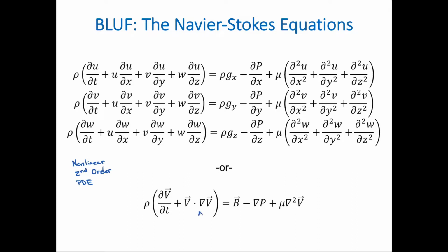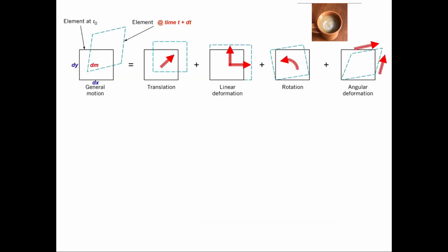So this is the del operator. We talked about it in lesson 24. This is the gradient, which is equivalent to the del operator. Remember we talked about pressure gradient in your lab, similar to the del operator, and this here is the Laplacian, essentially del or gradient squared. And that shorthand describes all three components, or all three vectors, of the Navier-Stokes equation.